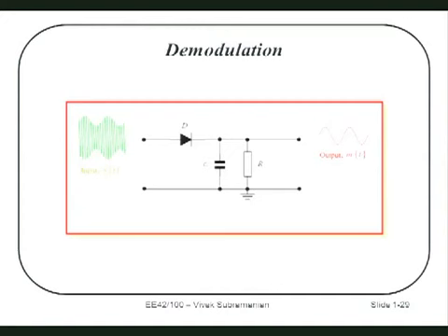How does it cut out the high frequency? That's a good question. It turns out that the amount of current a capacitor will allow to flow through it depends on the frequency. Higher frequencies are able to go through capacitors more easily than low frequencies. So the high frequencies just go through the capacitor and don't get to the loudspeaker. The low frequencies get to the loudspeaker.